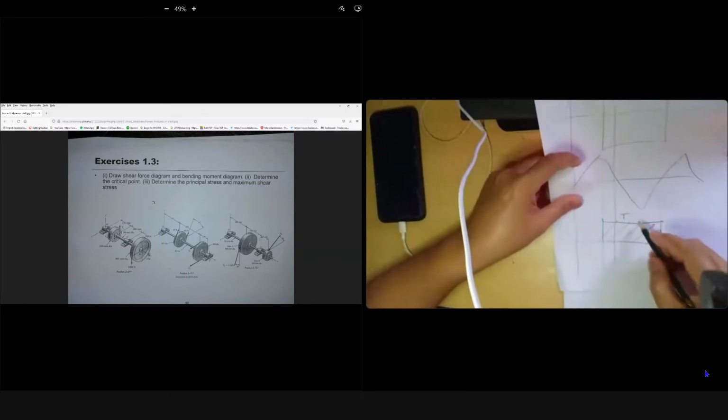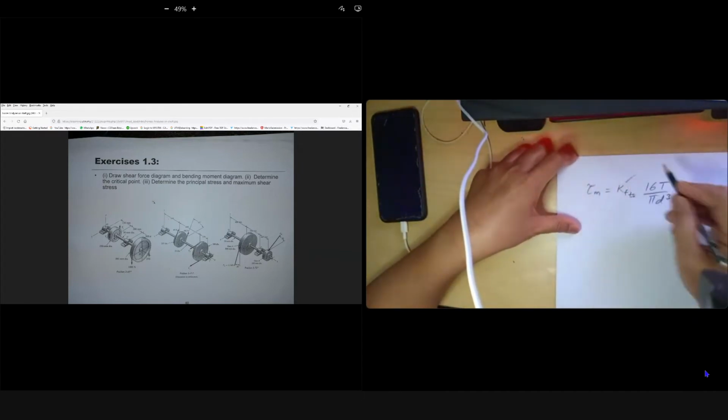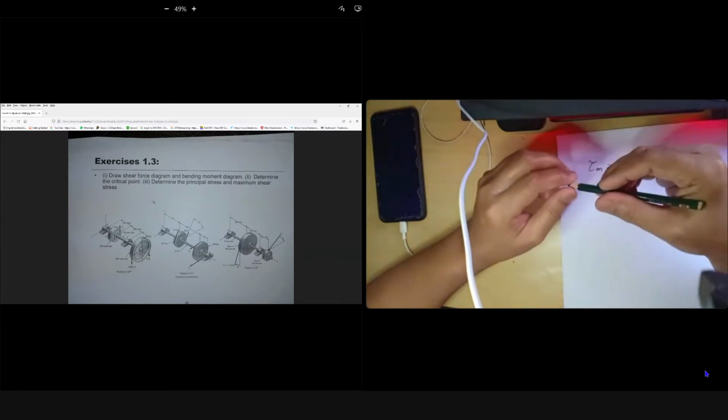So what is the torque? Torque is from your torque diagram. As I told you, it is the tension of the cable on the tight side times the radius, minus the loose side times the radius, giving your total torque. If given, use that value. So this will be in megapascal. After that, what do we do? We need to find the safety factor and SN, the endurance limit.